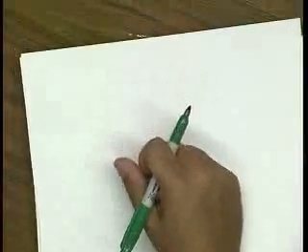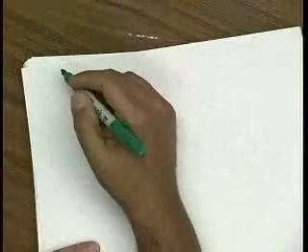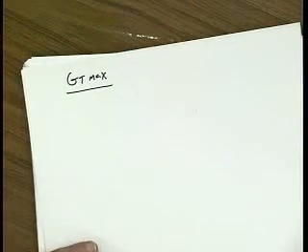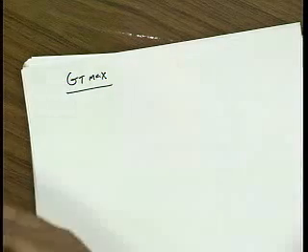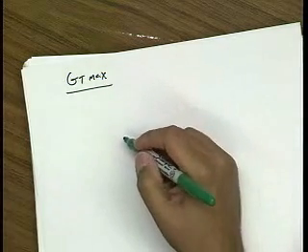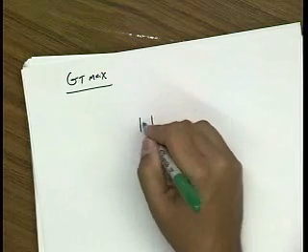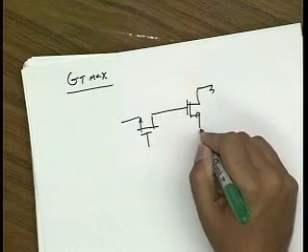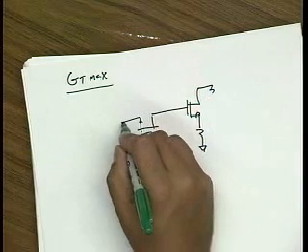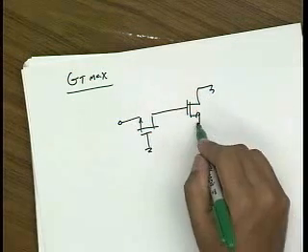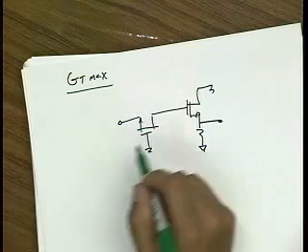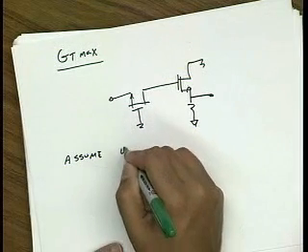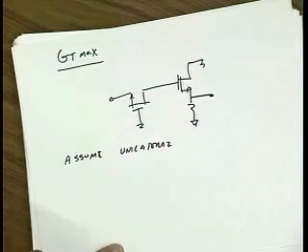All right. So the next problem, it's surprising how many people miss this, says to calculate GT max and just explain your assumptions, right? So a few pages back, we have a formula for GT max for a unilateral device. The question is, is this unilateral? Okay. So if I look at this amplifier, and I make the assumption that it's unilateral, so I just say assume unilateral, then the answer becomes very simple.